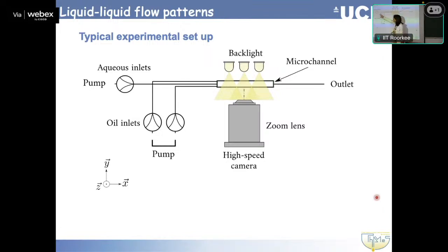But it's quite simple. You have two pumps, which at this scale are also quite often syringe pumps. And you bring your two fluids, in this case two liquid phases, an organic and an aqueous, or an oil and water, to the inlet of the test section. The inlet can be a lot of different things: T junctions, Y junctions, cross junctions, flow configurations. Then the simple first experiment for flow patterns is to observe with imaging. I think you are doing a tutorial as well based on that. There is a lot of work on how we image and how we account for the various effects. But basically we see the flow patterns, and that's why, especially in the lab, at least initially, tubes tend to be transparent. Then there is an outlet, and things can happen. If we have a reaction, we might collect samples to study concentrations or whatever else we want.